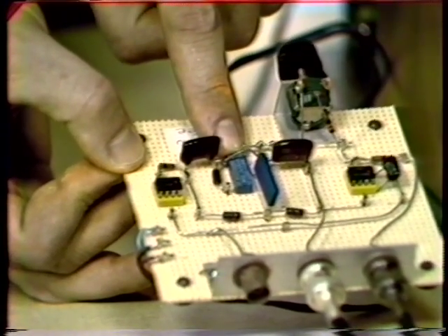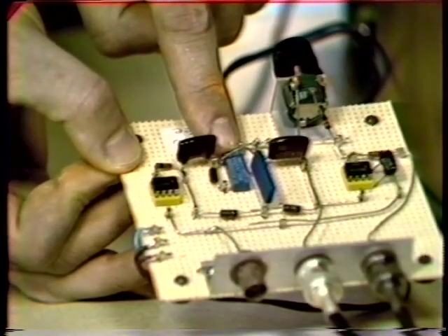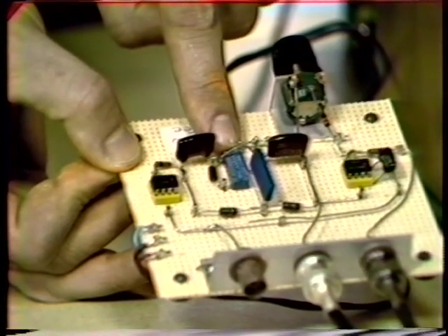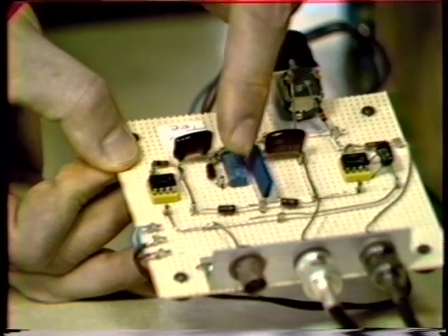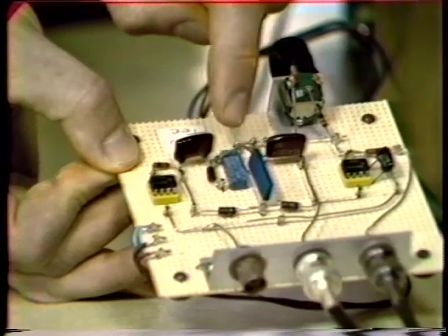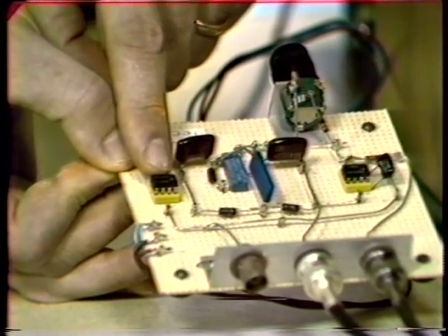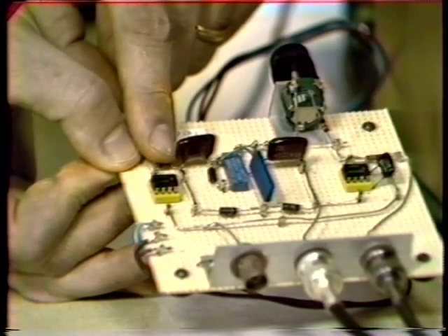You can show that you can null the network and cause it to have zeros on the imaginary axis by adjusting any one of the 6 components. The easiest one to do in this case was the resistor in the vertical leg of the T, and that's what this potentiometer does. And there's a buffer amplifier that just minimizes loading on the T network.